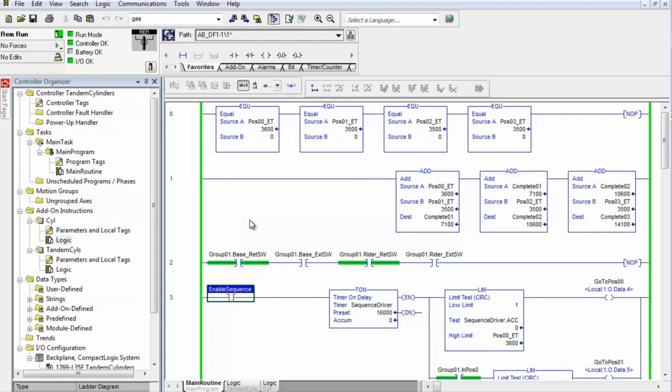So we've got these 4 toggle switches, and I try to give you some graphics in the manual to help you keep track of what you're doing with your actual I/O addresses or your switch positions. That's position 0. In position 1, which is the second position, the base cylinder is extending. The retracts, watch the line right here. Watch these 4 switches. The first thing you would see happen is the retract switch would go off because the cylinder is traveling, and then it would make the extend switch.